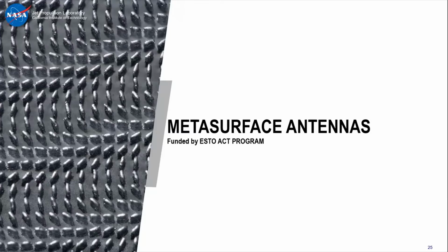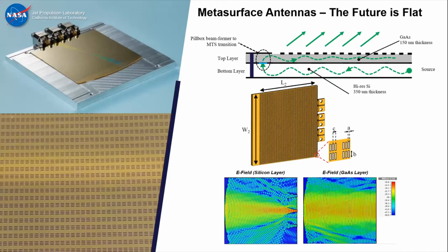So the first one is this flat antenna that has a 3-beam. We're taking advantage of a quasi-optical feeder, which is called a pillbox, to achieve 3-beam pointing. And all we do is, by offsetting 2 feeder horns, exciting a reflector, which is a flat reflector here, we can excite the top layer through these coupling slots. We can excite this top layer and then we can use any type of metasurface on the top layer to get the beam that we want.